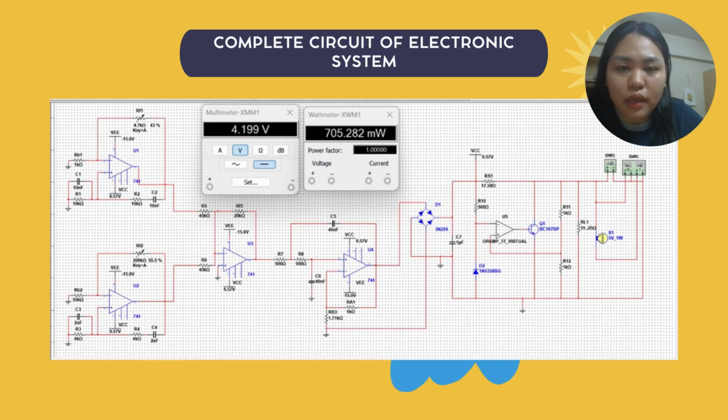Coupling capacitors C1 until C5 for signal AC filtering. Feedback resistors, which are RF and RG, control gain. Biasing resistors and power rails, which are plus VCC and minus VEE. This points out that each op amplifier stage boosts the signal strength progressively.